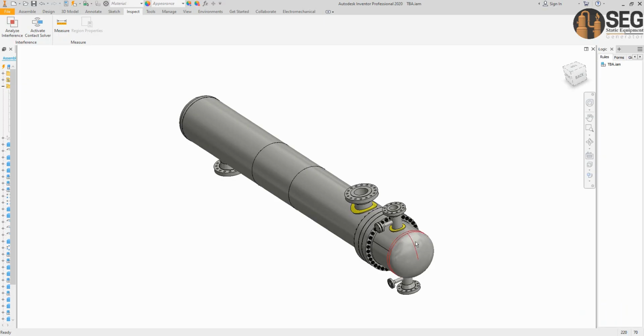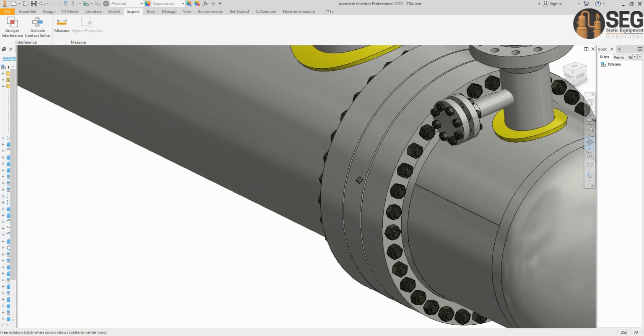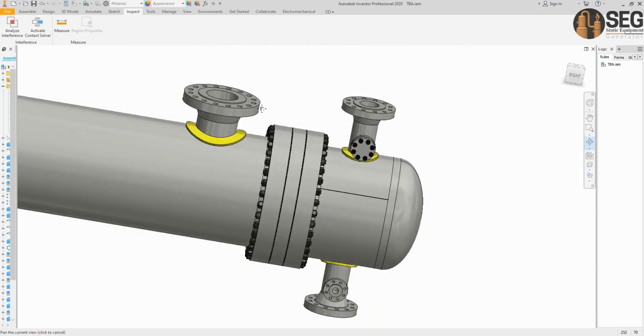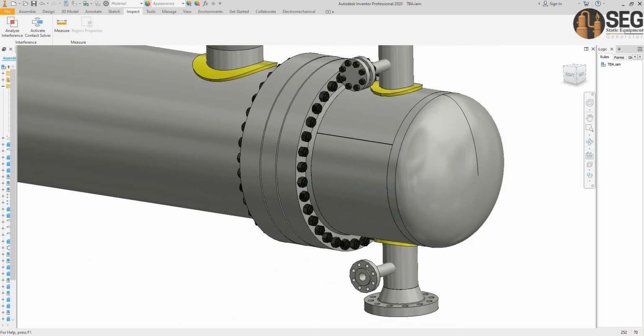Okay, the same way you can take a copy from the gasket and the blind and paste it for the other nozzle down here, which is A01, which is that one. Here we have these stud bolts for the top nozzle, which is that one. The same way, you can take a copy of the gasket from top to bottom, and let's try that.